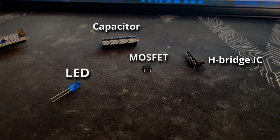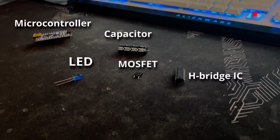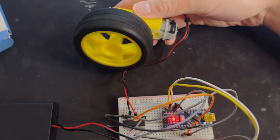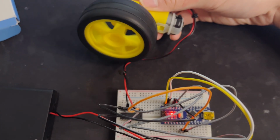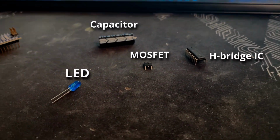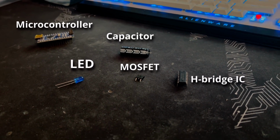And that leaves us with the other stuff in electronics. Things like LEDs, MOSFETs, H-bridge chips, and capacitors. Some of these help to make the microcontrollers, actuators, or sensors work better, or just outright work. For example, in between an Arduino and a motor, there would have to be a MOSFET or an H-bridge driver as an intermediary. This is because the Arduino can't provide enough current through its pins. That's just the surface level explanation of how the extra components work, but the point is that they are able to make the main components work. There are many components which I can't cover in one general video.